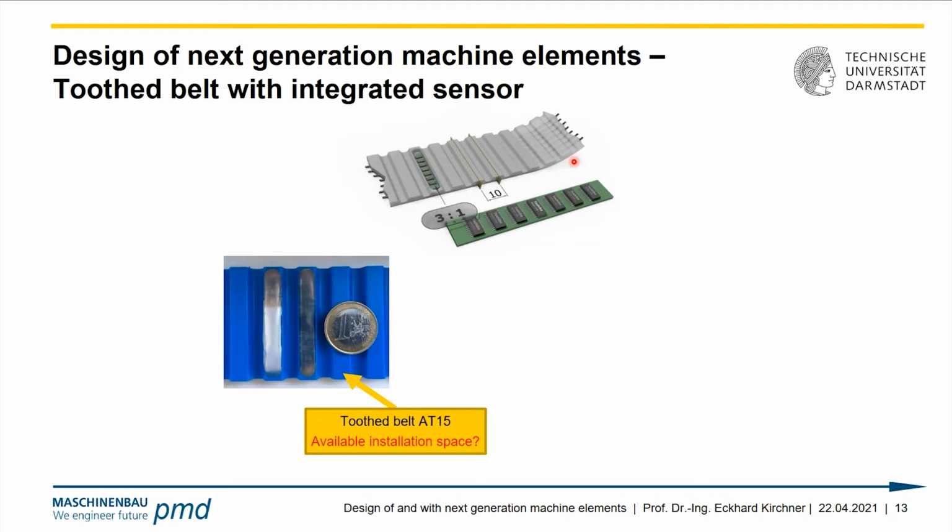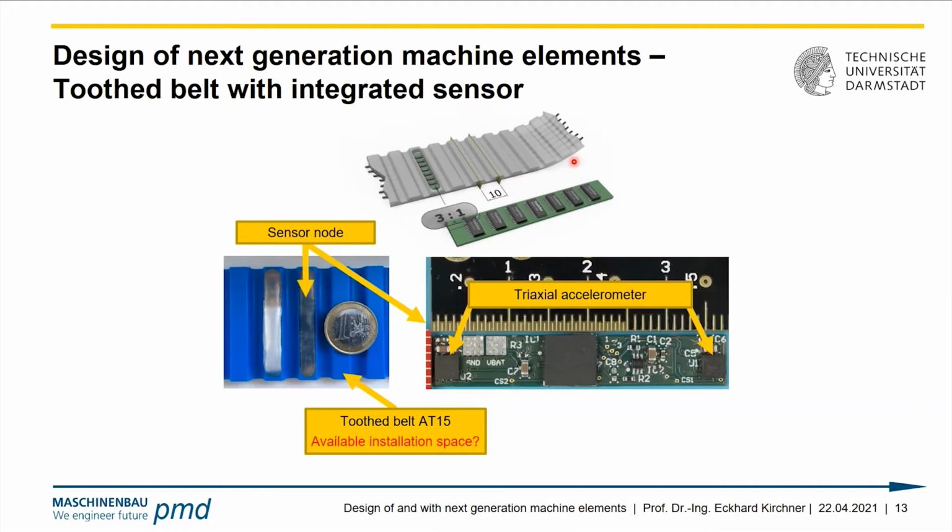The steel strings, they deteriorate with usage time. The stiffness changes, and with that, the force inside the tooth will change. In order to measure the span-specific forces inside that tooth belt, we applied 2 accelerometers to that sensor chip here.